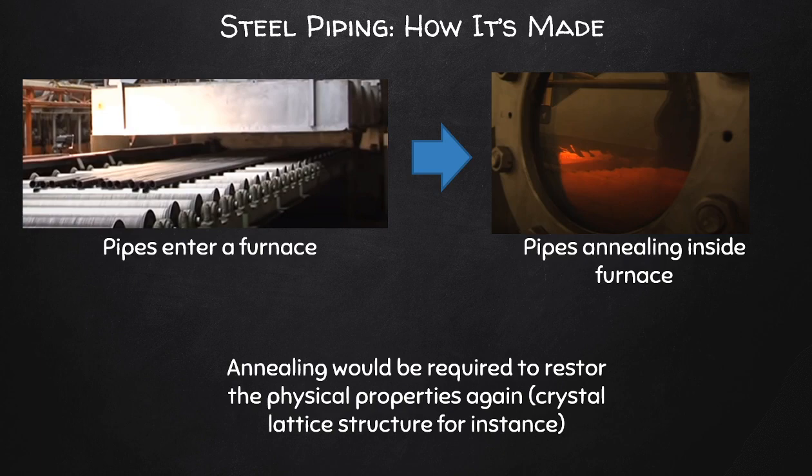So this fabrication process tends to form very rough surfaced pipes. You can imagine. So you can see those pipes lying there on the rollers. They don't look very, very shiny, so you can imagine how rough they are. So these pipes would require further refining in order to reduce the surface roughness, but obviously this will cost more money, and we tend to use the pipes therefore as is, unless we really, really do require smooth pipes. But then you're going to pay out of your pocket.